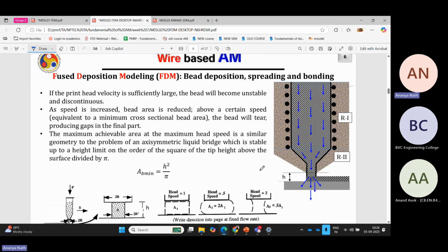There will be some waviness, but not that bad a surface. So it's important to control the process parameters to get that smooth surface, because the more you lower the post deposition cost, the more you ultimately lower the whole printing cost. That's why we do not want to do a lot of post processing, and that's why we are concerned about the process parameters.